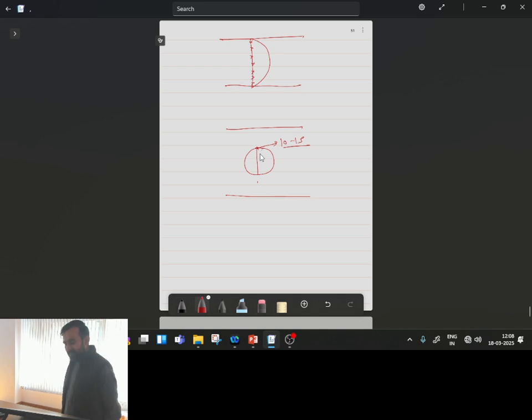So it means that with the techniques we have discussed, cross correlation and hot wire anemometry, we cannot simultaneously measure the velocity field at a large number of points.